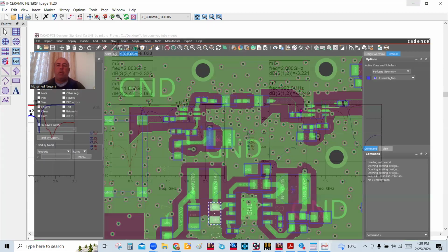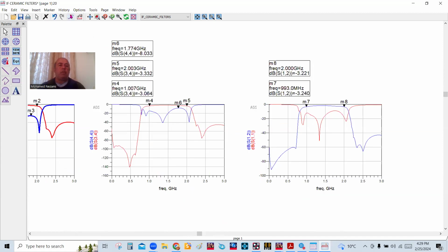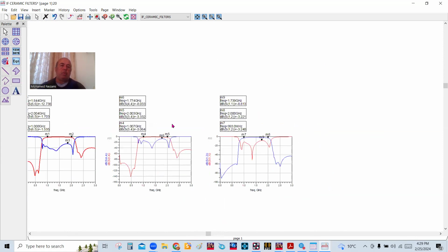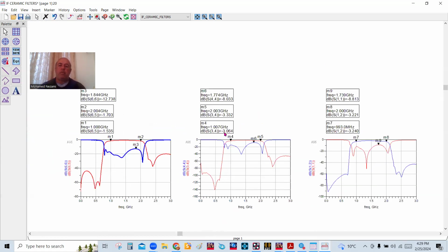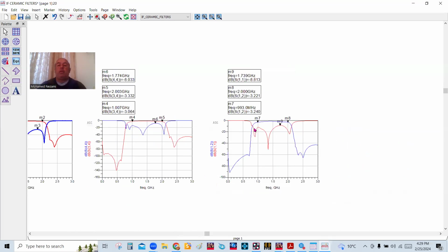Then the return loss worst case is about minus 8.8. So it's almost the same as if you put the two things together. It got a little improved, of course, because of the copper 50 ohm line, or 75 ohm, interstaging between them. So that's what we get.